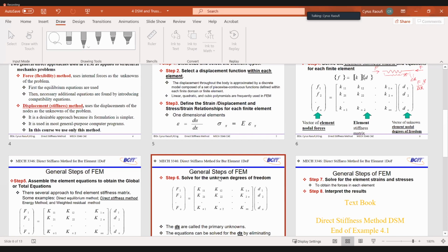You need to have a part, you need to apply force, you need to use strain gauges to measure, for example, the strain and stress and compare with your result, right? That is not always possible because it needs some sort of physical setup. But that's the best if you can end up with some sort of physical setup to make sure that you can rely on your simulation result.